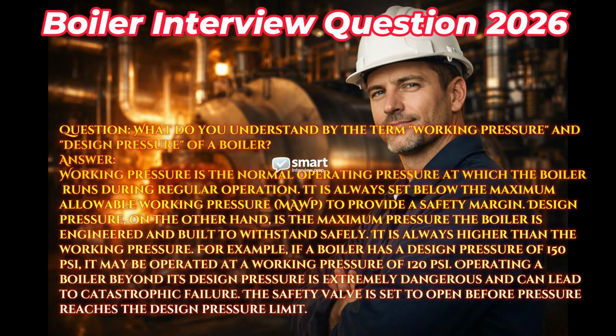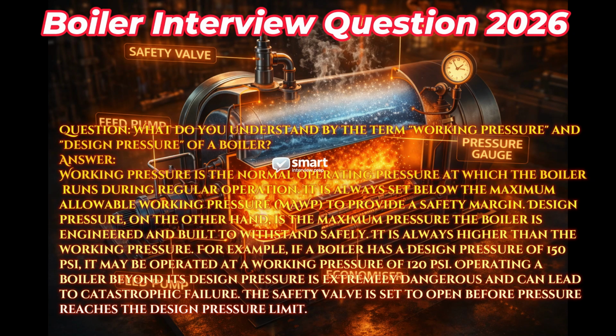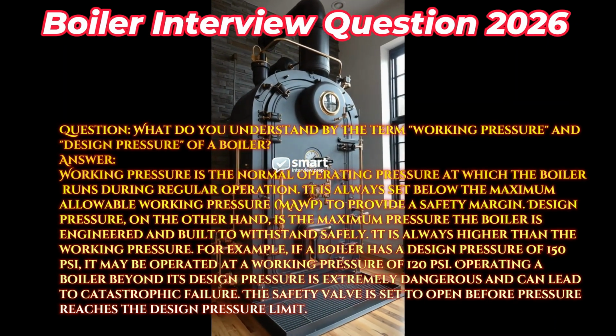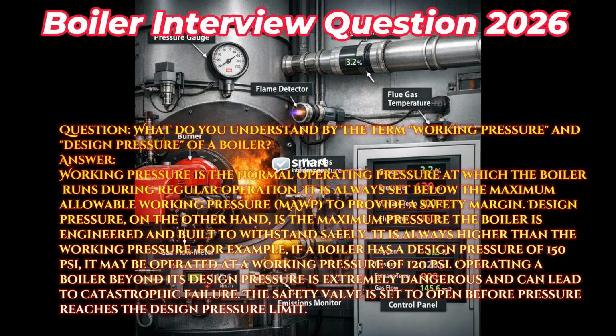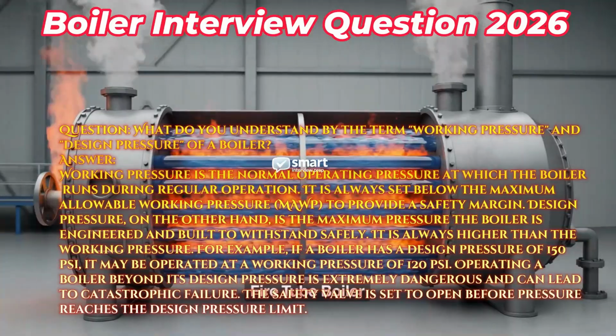Question: what do you understand by the term working pressure and design pressure of a boiler? Answer: working pressure is the normal operating pressure at which the boiler runs during regular operation. It is always set below the maximum allowable working pressure, MAWP, to provide a safety margin. Design pressure, on the other hand, is the maximum pressure the boiler is engineered and built to withstand safely. It is always higher than the working pressure.